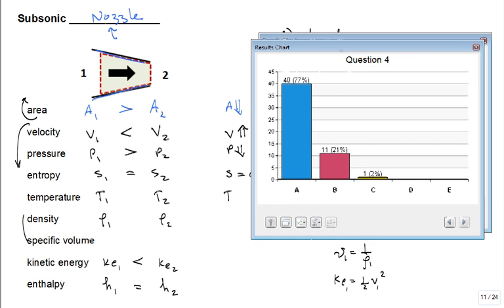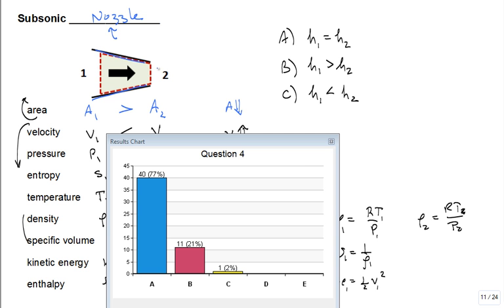Okay, now let's do this. Before I spill the beans, what does this dashed line indicate? It's a little symbol for CV, control volume. What can we do with the control volume? Mass balance, energy balance, and we could do entropy balance. 3 balances. Now those balances could account for transient effects as well as steady state. Almost all of our problems are steady state, right? So for the mass balance, what type of equation do we get? M dot in is equal to M dot exit. M dot's equal to M dot.